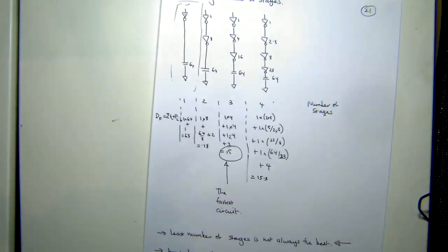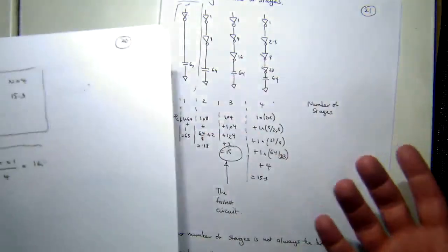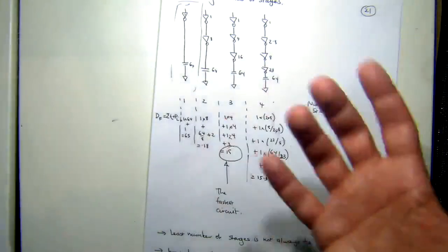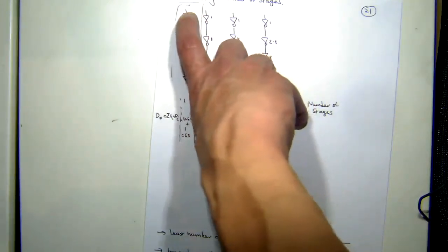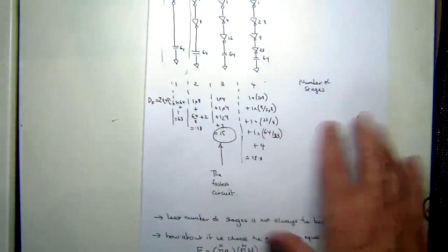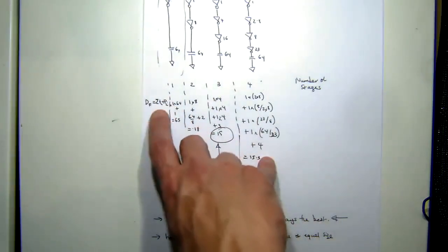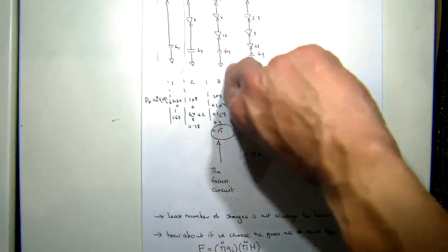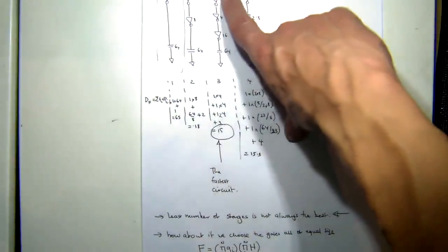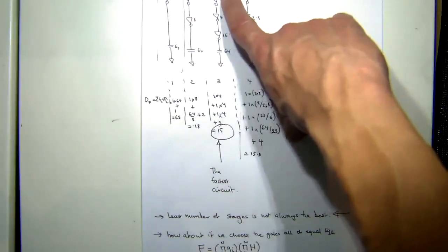It's showing you that by adding an appropriate number of inverters, you can actually do better than just trying to drive with one drive stage. Essentially what we did is we calculated the total delay in terms of logical effort, path effort and parasitic delay, and we worked out that this one was the one that gave us the minimum delay. The fastest. Minimum delay, fastest.